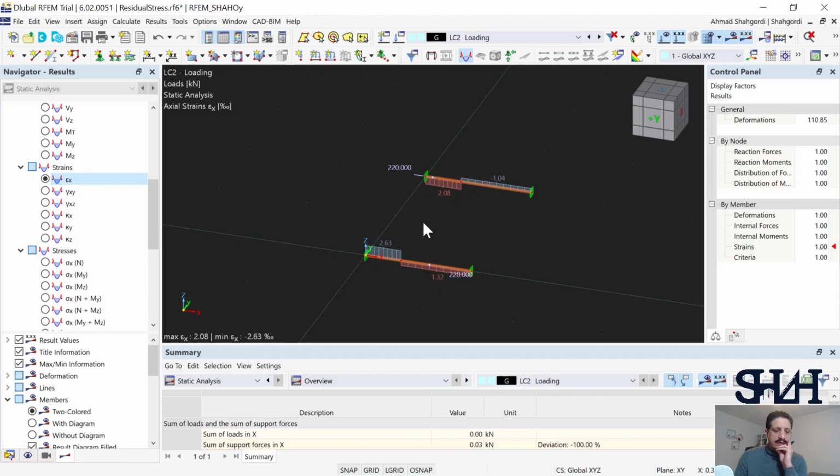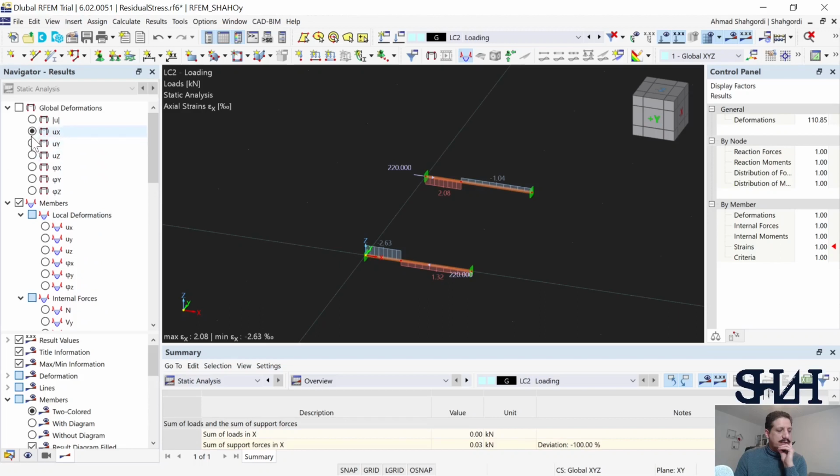What kind of strain do we have? Or in a better way, to calculate with the deformation. So in the loading phase, it goes up to minus 1.052, and then it will come back for 0.83, which means that minus 1.052 plus 0.831, and it will be 0.22 in the negative side. It means that point C will shift towards A or to the left with 0.22 millimeter as a permanent deformation. That's how we can summarize this calculation.